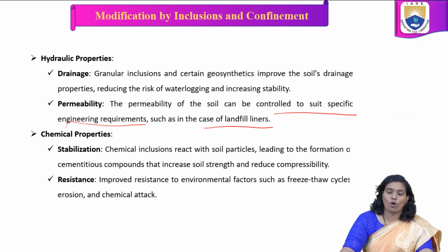As per chemical properties of the soil, because of modification by inclusions, stabilization occurs: chemical inclusions react with soil particles, leading to the formation of cementitious compounds that increase soil strength and reduce compressibility. In resistance, they improve resistance to environmental factors such as freezing and thawing cycles, erosion, and chemical attack.